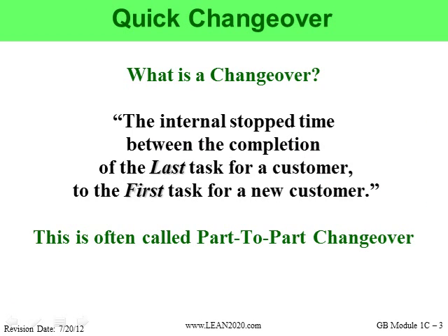So when we talk about changeover, we're going to talk about the time that the machine is idle or your process is idle from when you've completed your last part to when you're producing parts of the next part number, okay, or the next lot. So that's the time that we're talking about. That's our changeover time, and it's often referred to here as part-to-part changeover.